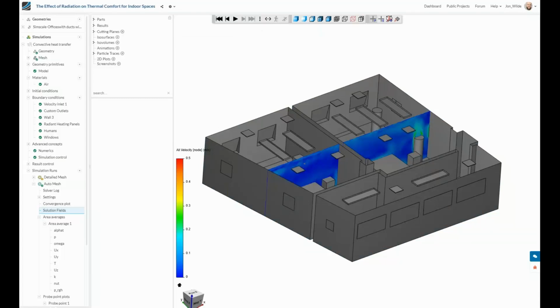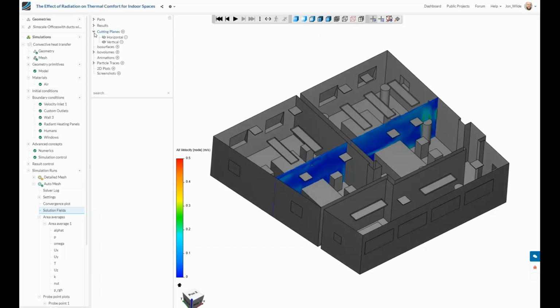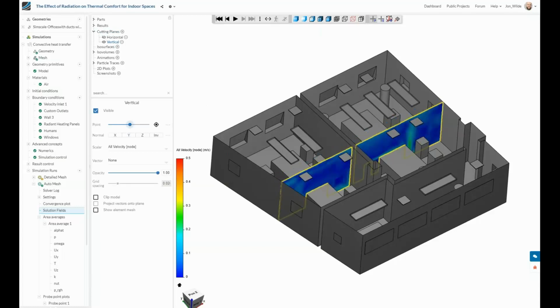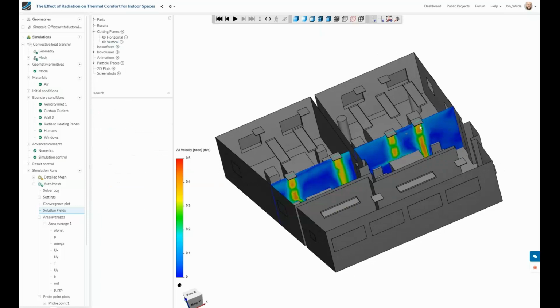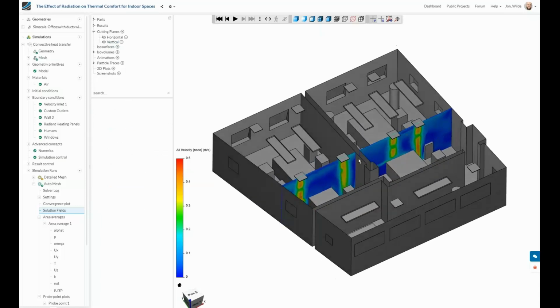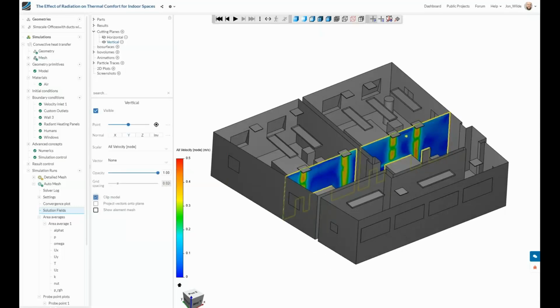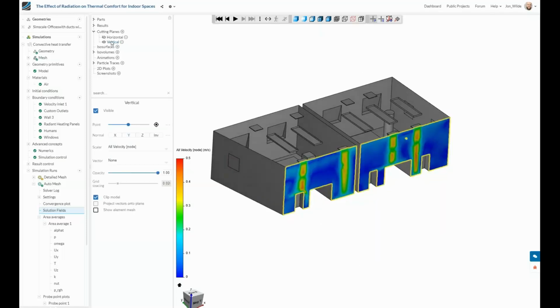Okay, and then once it's loaded, again, I've set up a few different things that you'll be able to take a look at. We've got a cut plane here on the cut planes, and I've called it vertical, and we could move it around a little bit to maybe the same point as before. So now it's underneath one of those vents. We can get an idea of how the flow moves around the model. It might be better to clip it and cut the model in two, and then we can get a little bit of a better idea of what is happening inside.